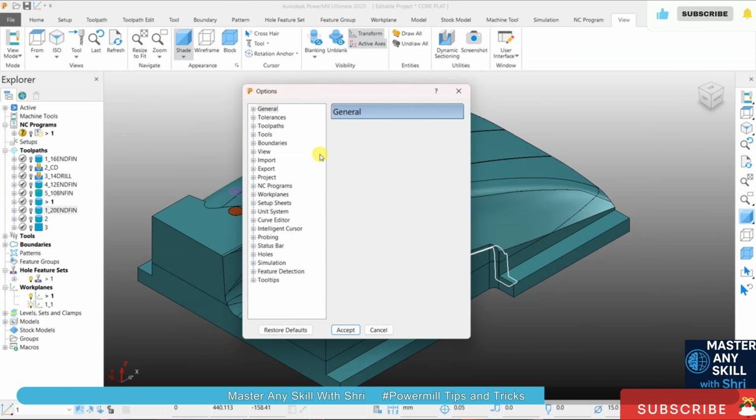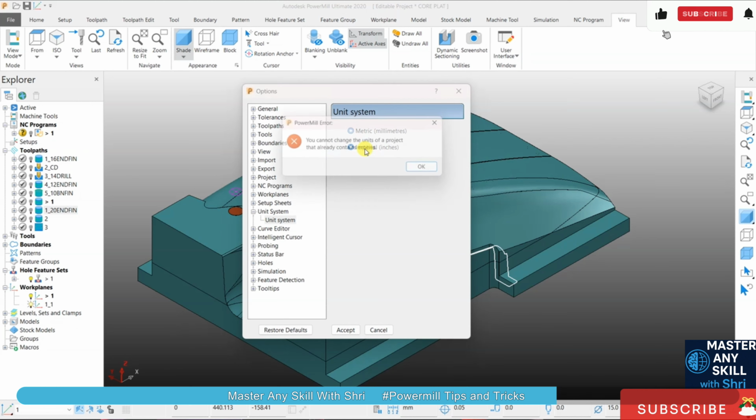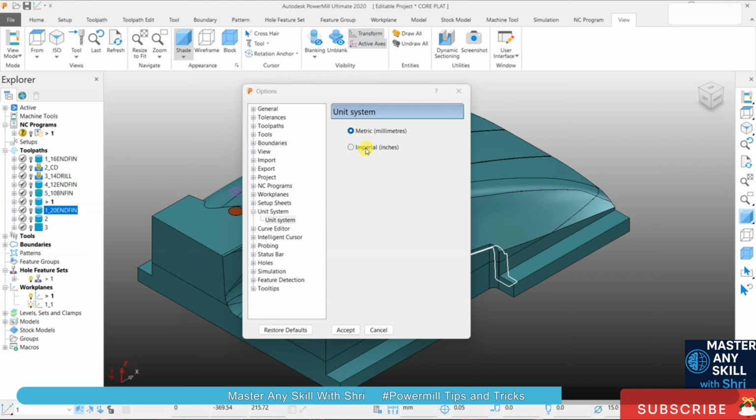Now again come to this, and from customization we have this application option. From application option we can change the unit of our project. Here we have the unit system. Click here. Now it is working with millimeter. Now if you want the metric, you can switch it, but before it you have to close this project, then only it is possible to switch to another unit.